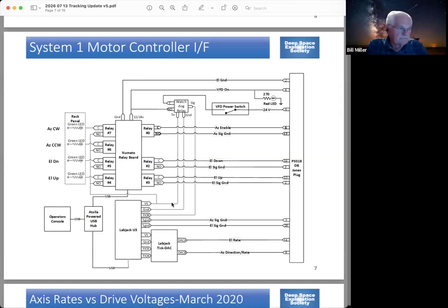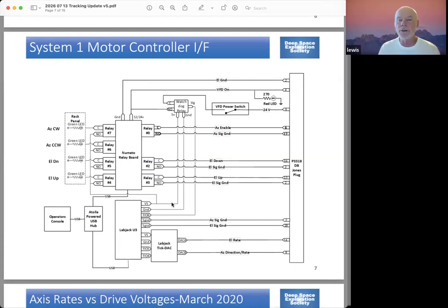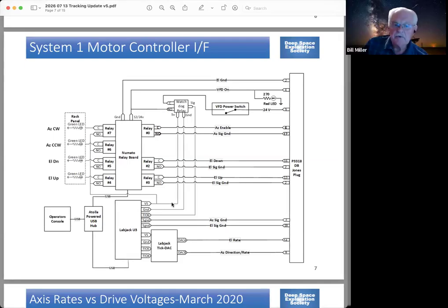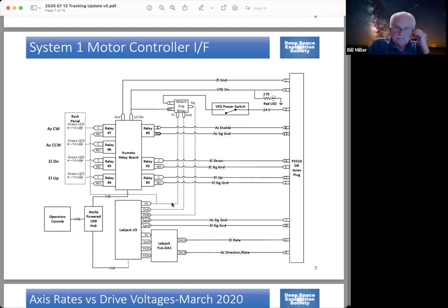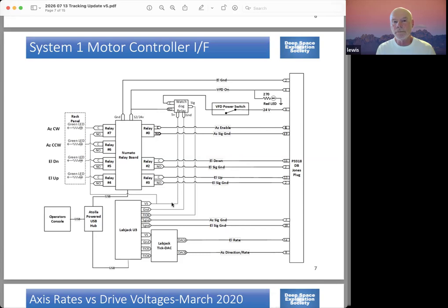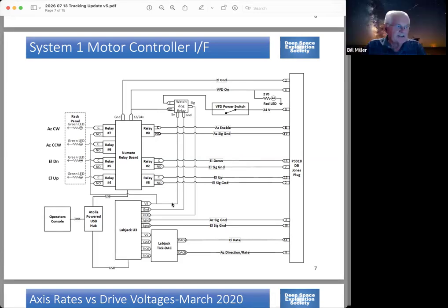Primarily the requirement is that you want to make sure that you can't get both connected at the same time. The Jones plug ensures that you can't have it plugged in twice. The other thing we discovered is you can't move the Jones plug with the power applied. If you do that, it can cause trouble.